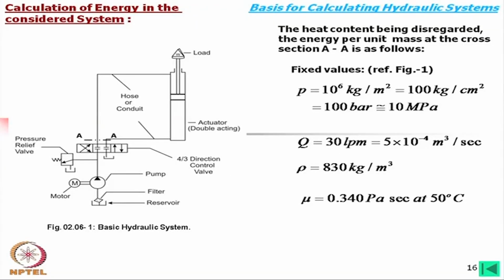Whereas in India, when the ambient temperature itself becomes 50 degrees centigrade at some places, 45 degrees centigrade at least in summer, hot summer, then oil temperature may go up to 75 degrees centigrade, but temperature more than that I would say is not allowable for the oil.